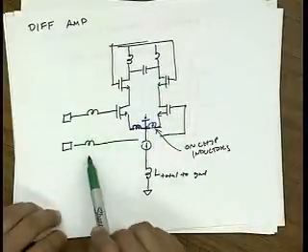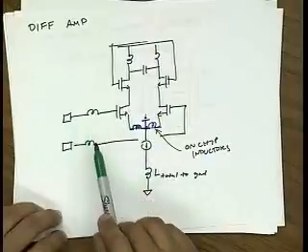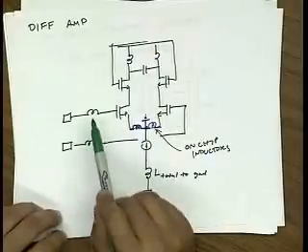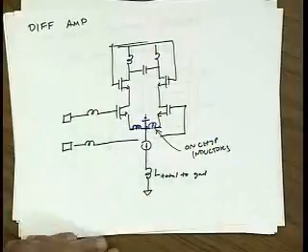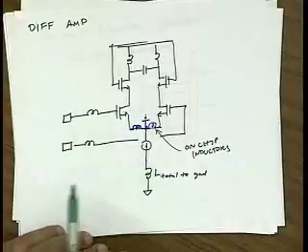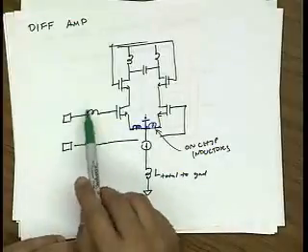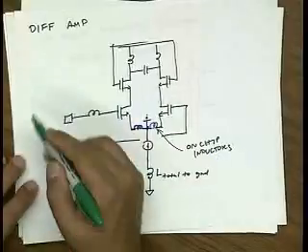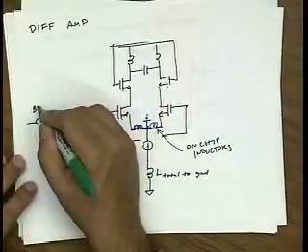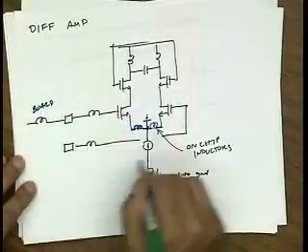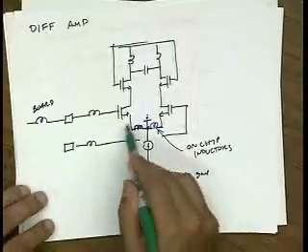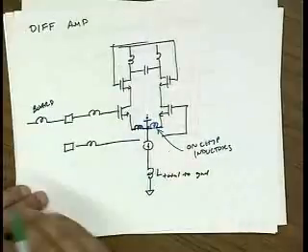And these additional inductances are all on the gate. And those I can use basically to fine-tune the frequency. So this differential topology has a big advantage in that I can easily just change the gate inductance on the board. So this is the board, let's say, contribution, to get an input match and not worry about messing up my 50 ohm input match.